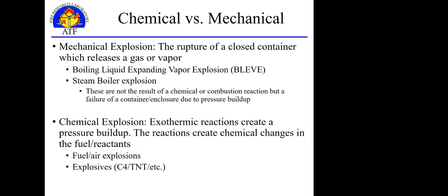You can have a failure of a propane cylinder due to external fire impingement, and then the container BLEVEs and we get a big fireball. But that's still a mechanical explosion that just results in the combustion of the fuel inside the container once it's released. Versus what we're typically dealing with in a structural explosion, which is going to be a chemical explosion.